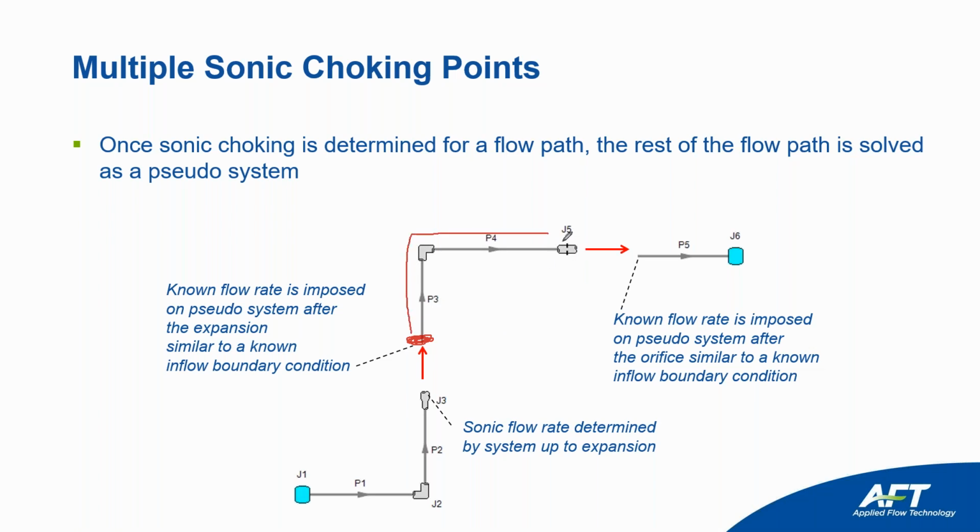But here's the thing: at this orifice plate, we have a hiccup. We have a discontinuity where we really don't know what's going on inside that pipe yet. That's where we actually start from the discharge boundary and we work our way backwards. We know the marching methods, we know the pressure right here, and we know the flow rate and the energy across this boundary because again, it has to be able to balance.